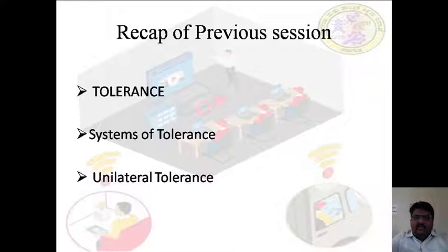Tolerance can also be defined as the amount by which the job is allowed to go away from accuracy and perfectness without causing any functional trouble when assembled with the mating part and put into actual service.